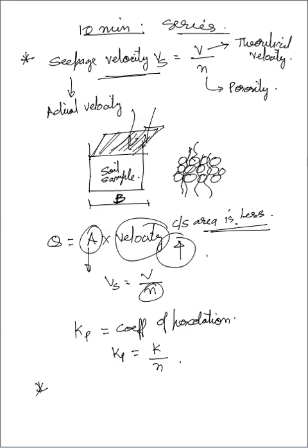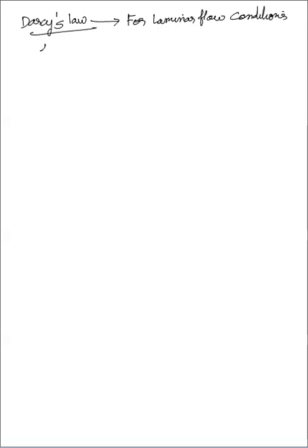Remember another thing. Let me change the page. Darcy's law, you can also study it in the permeability chapter. It is specifically for laminar flow. Remember this, it is for laminar flow conditions, and the second condition is in a saturated soil.